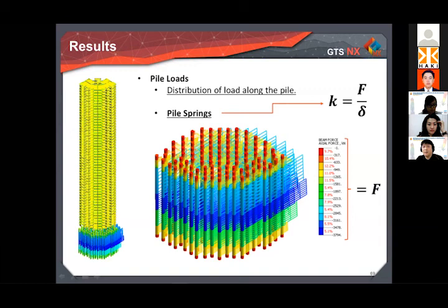The reason for this is mainly because of the positions of the pile inside the raft, which can be affected by the load location of the column, due to pile group effects, which tend to decrease the deformation of the pile, meaning that some may not offer the same reaction as others. So the generated springs for each pile may be sent to the structure team or simply exported back to Midas Gen, as I mentioned previously. And the very same thing can be done for area springs.